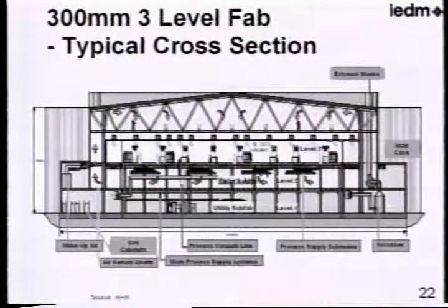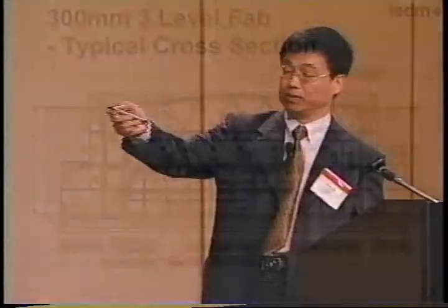So the electric power usage also has to increase. So the utility hierarchy is quite different. And also the two-stage design for the scanner is much heavier. Because 90 nanometer and 65 nanometer advanced technologies are being developed, the floor strength or vibration spec is also much stronger. So this wafer slab will be thicker.